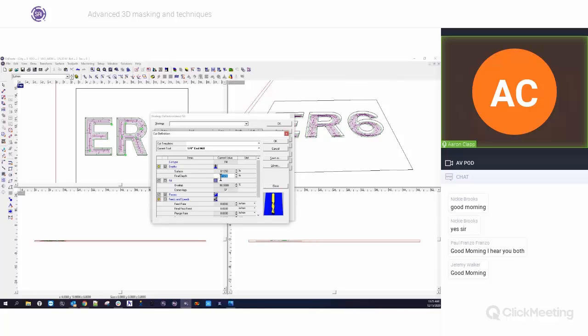The problem you may end up with is if I just put in the depth and left my surface at 0, what might actually happen is the toolpath might not act properly, and you might not get the expected result because it's basing all of its mathematics on the idea that you still had your 0, 0 at the top of the plate. It thinks there's still material there. So you're gonna get something that you don't want. And that's where the surface setting comes into play.